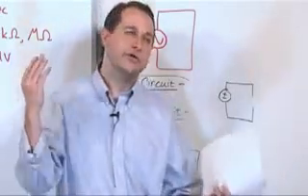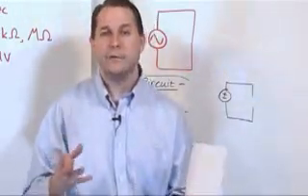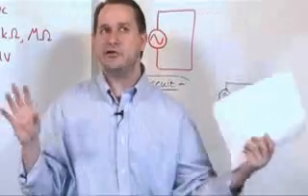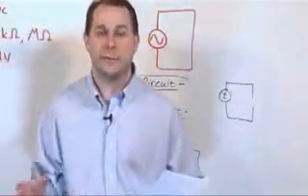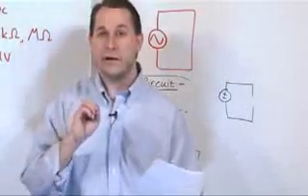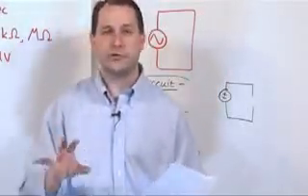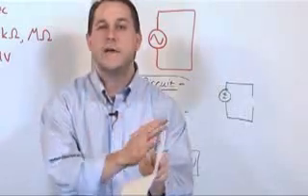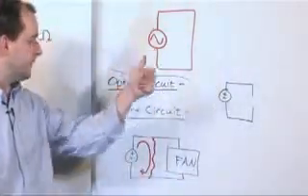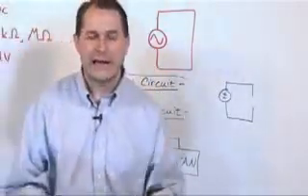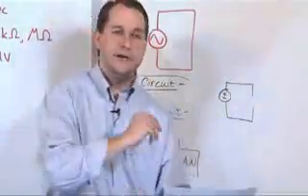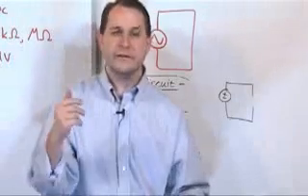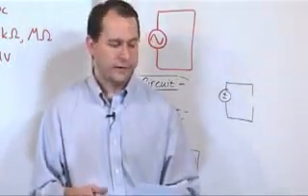And that's why you have those circuit breakers outside of your home. They are there to detect if any short circuits happen, to detect the increased current that comes from it, and to shut them off. If you get a short circuit in your washer or your dryer, maybe some wires start to touch, the current is going to go up really, really fast through this tiny little leg, and your circuit breaker is in the circuit with that. It detects that, and then it shuts the circuit down. So that's basically how that works.